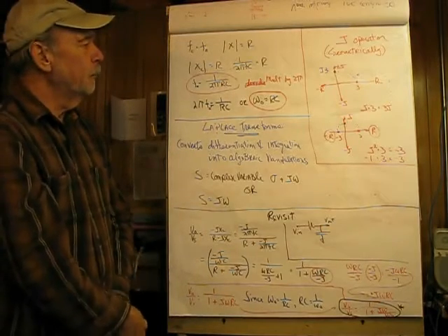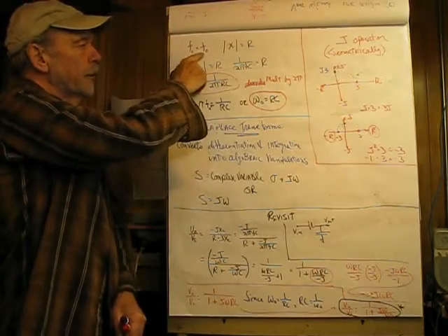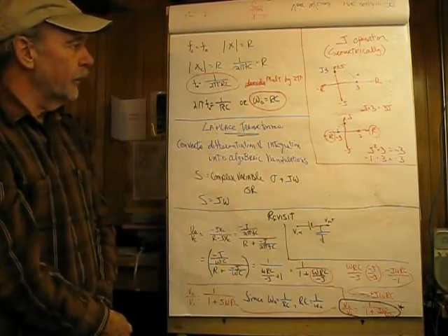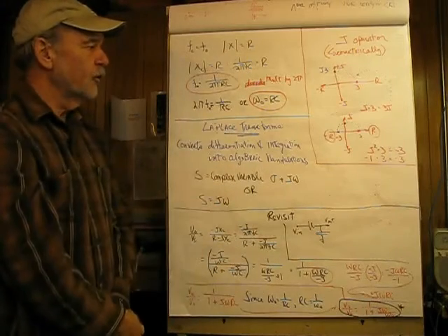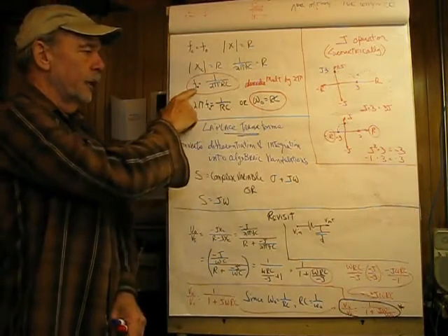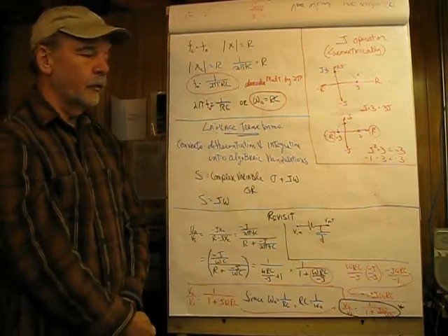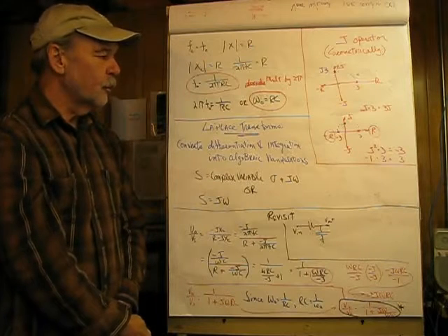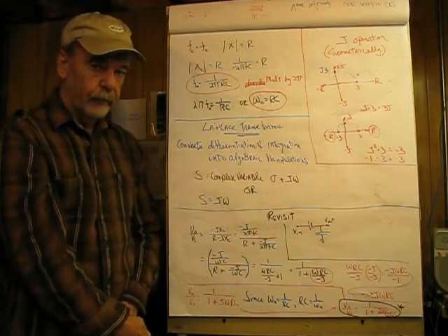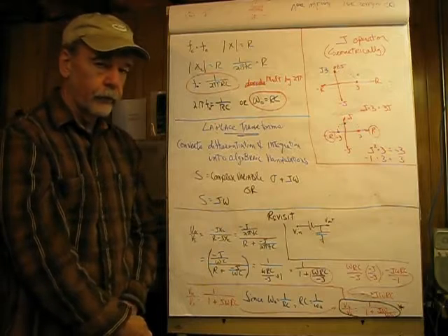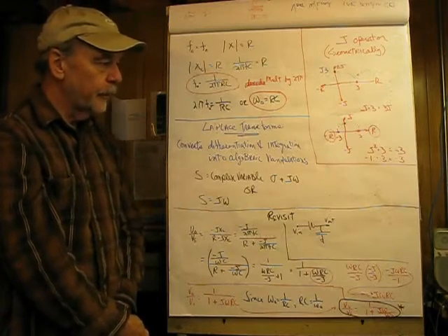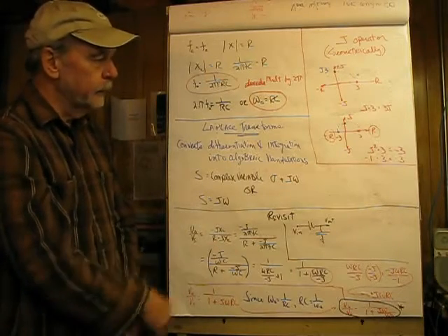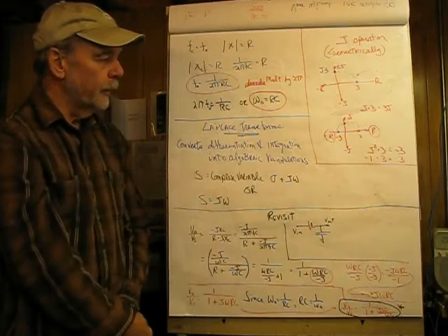Okay, let's back up to here, and our F critical now, I'm equating that to F0 just as a reminder that they're basically the same thing. Again, absolute value of X equals R, and then solving for this, F0 is going to be equal to 1 over 2 pi RC as it was before. Now what we're going to do is express this as omega 0, and this is the language of filters. It's not in frequency, it's typically in omega. Audio guys like frequency, but everybody else uses omega 0.